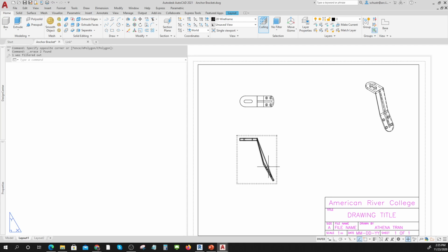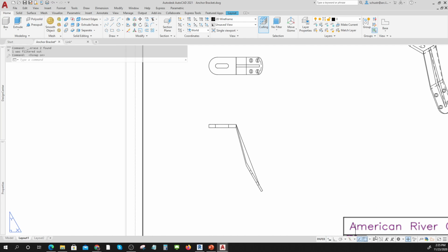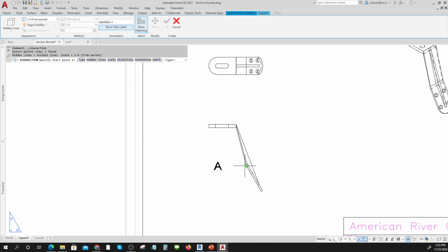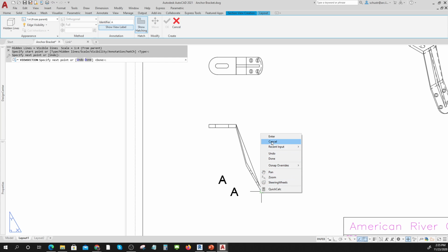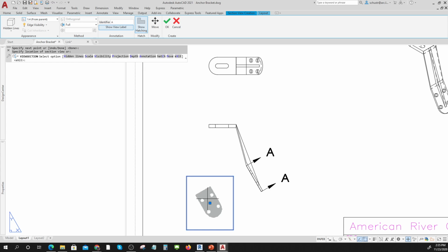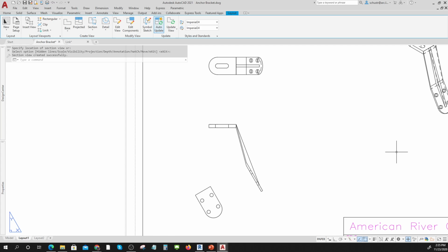I'm going to show you how to do that again. So here I am. I want this one at an angle. This time I'm going to turn my snaps on. And I'm on the layout tool, and I'm going to make a section view here, and I'm going to go right along that surface. Once I've picked two edges of that surface, I'll hit enter, and I'll just move it down here. I can go up here, but this is what I really want, is right down here. And it's looking straight at that. I'm going to click my left mouse, click, and then I'm going to hit OK.